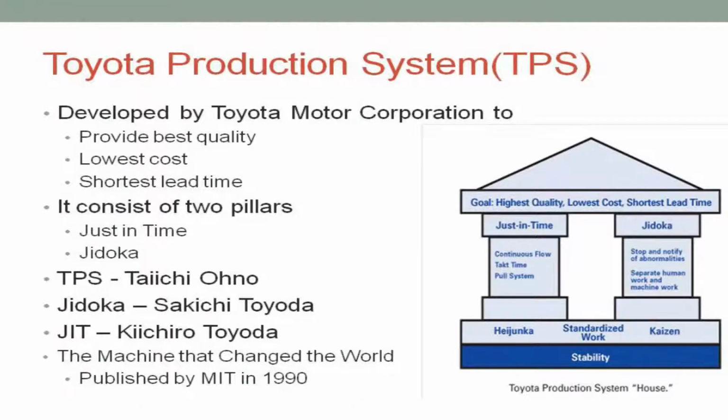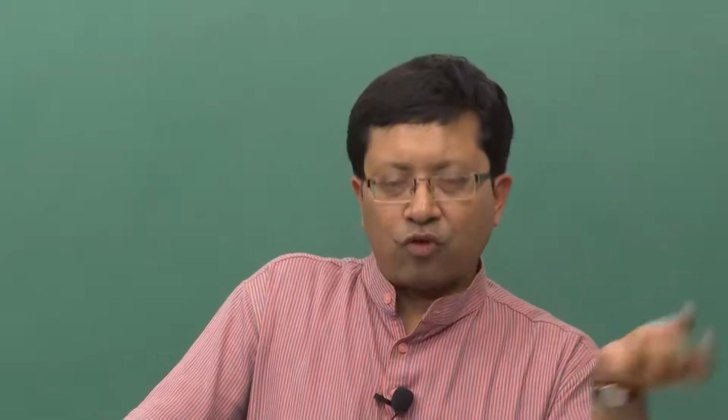Obviously you are not going to push the system, because if the inventory is already high, pushing would have a devastating effect in many cases. It is basically pull, such that the flow of materials is almost constant, and the stoppages of raw materials, work in progress, and finished products are minimal, because the more they stop, the more they are bottlenecks. The more they are bottlenecks, the more cost is involved. So the overall productivity of the whole system decreases.